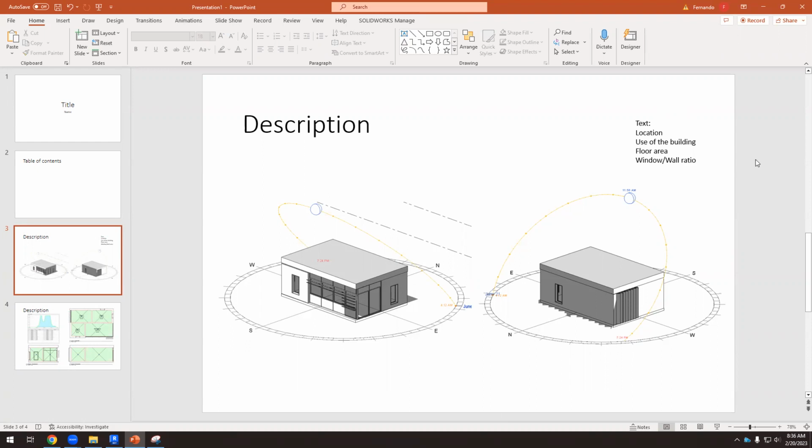because the first thing we found out last week is that the area of windows matters. It's something that creates a lot of cooling loads especially, if the windows are south, east or west oriented. In the north, it doesn't matter. Well, it matters in cooling and heating, but for solar gains, having a lot of windows in the south is relevant. So the window to wall ratio is the area of the window divided by the area of the wall.